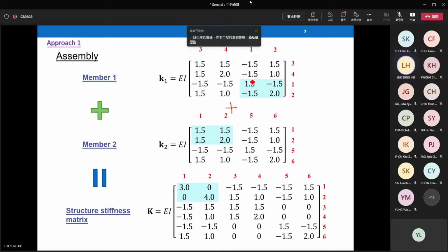How to add that all together? In topic 1, truss analysis, we introduced different skills. You may first sort this matrix so that the code numbers are in ascending order, and then enlarge this to a 6x6 matrix, filling the missing columns and missing rows with 0. You may do it in this way, or by direct observation, by direct mapping.